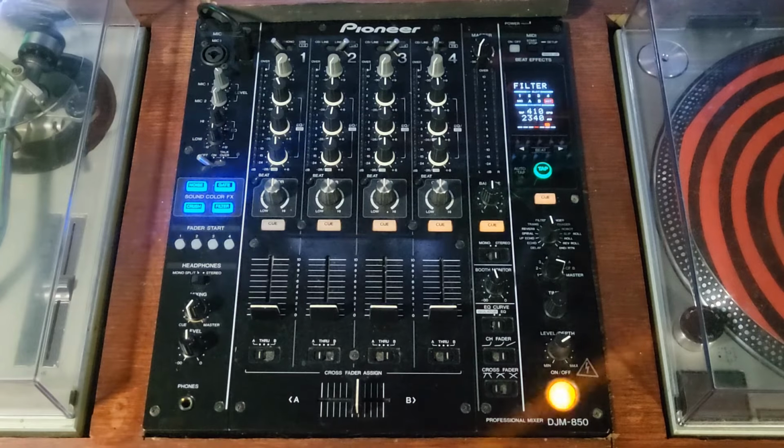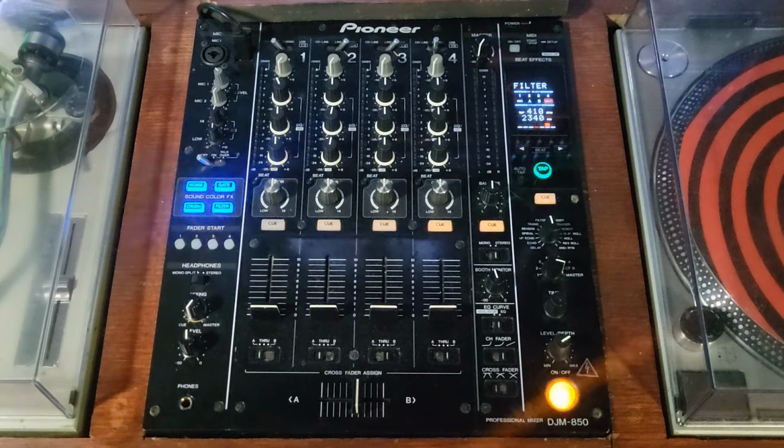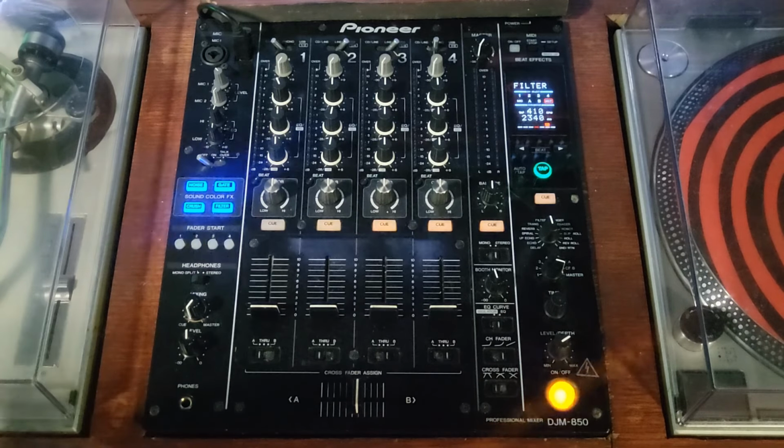We're also going to get into powered speakers, be it top cabs or subwoofers, and I may also touch on your music files. So, we want to achieve what we call unity gain with our controller/mixer. What this means is you're going to send the hottest signal possible out of your mixer controller without distortion. This is great for recording, and it's great for live performance as well.